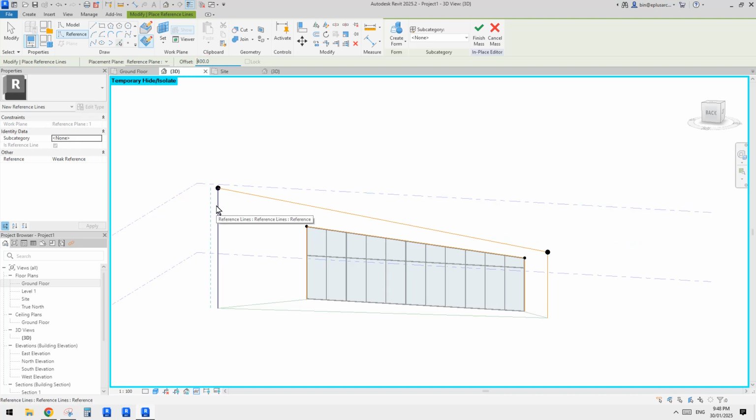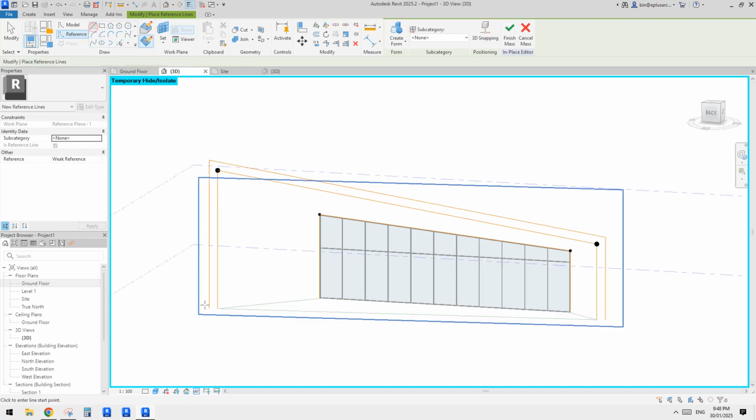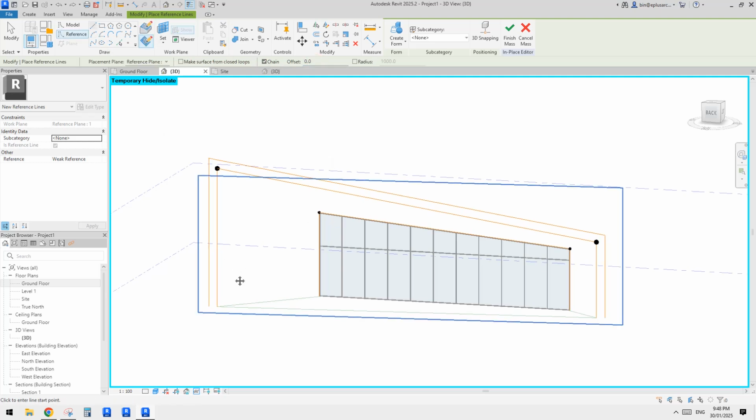So you can see roughly 400 is okay. And then we can just offset 1, 2, 3. Now we have this, and then of course we need to close. Without the offset, Control Z. Turn off the offset, 0, and then just finish this.